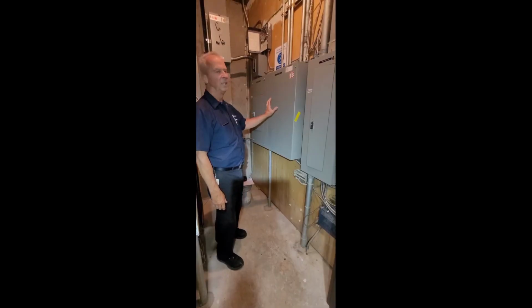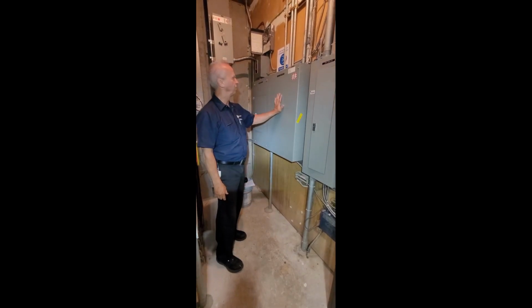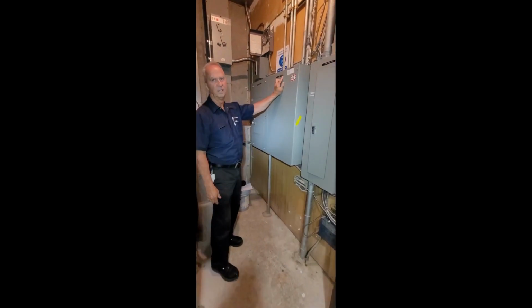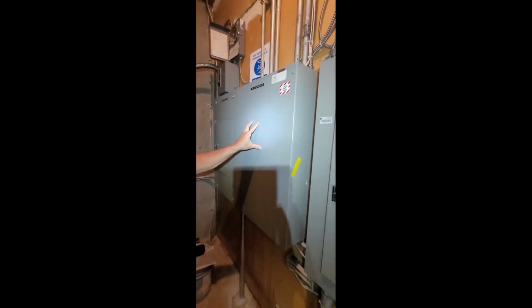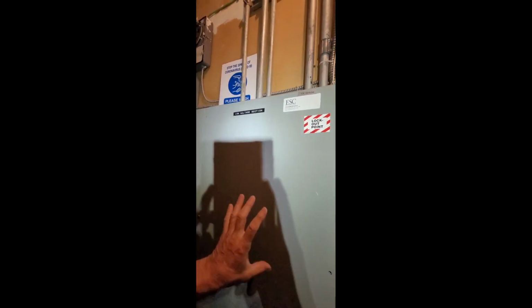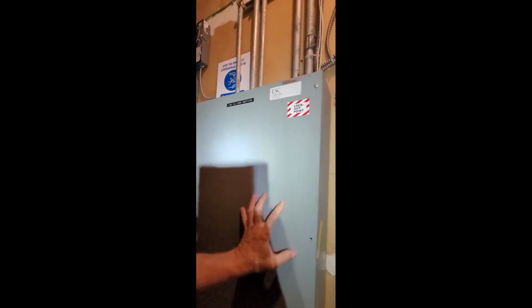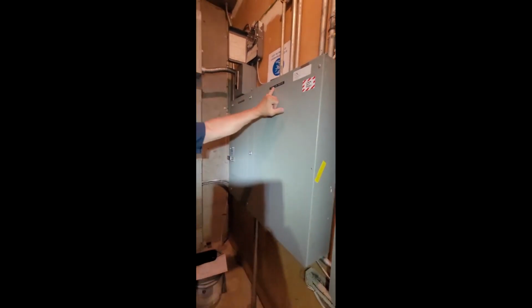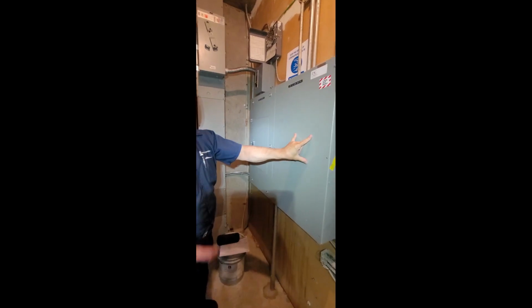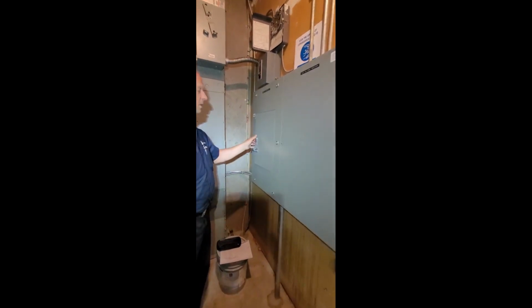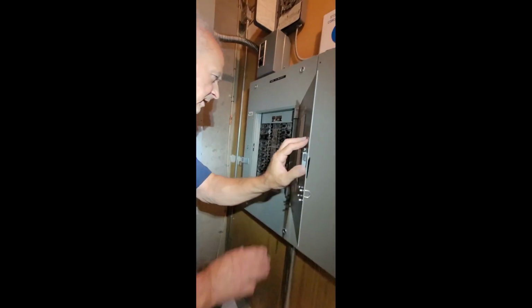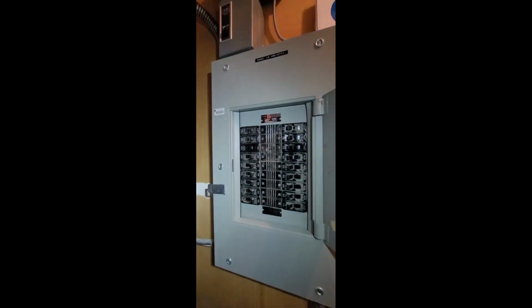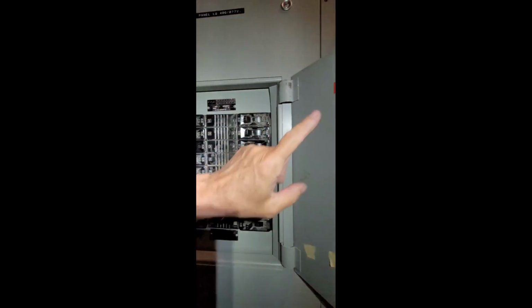Go to the electric room and we'll check. Every floor has a low voltage section, which is not totally correct. This low voltage section will be high voltage on the left side, low voltage on the right side. So these labels are incorrect. Okay, so don't always believe the label. The breaker panel itself will not show suite 651 on the directory card.